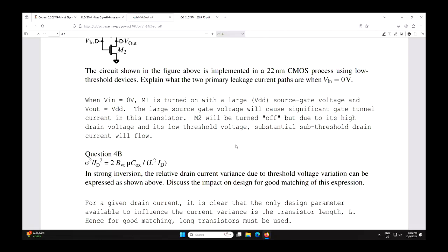So it would be a common assumption, looking at that, that the drain current is fixed. And then that leaves only that parameter, the channel length, as something you can influence. These are constants, so you can't actually change these. You can change the process, but that is not a circuit design decision or design parameter.